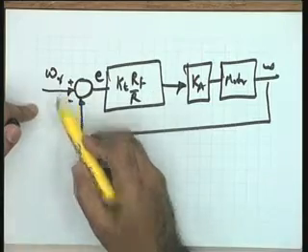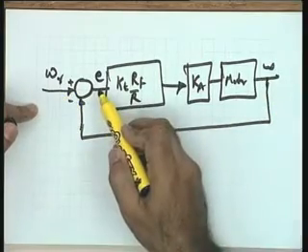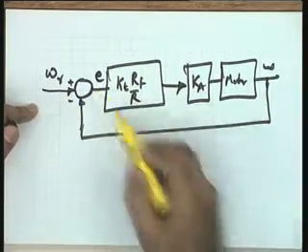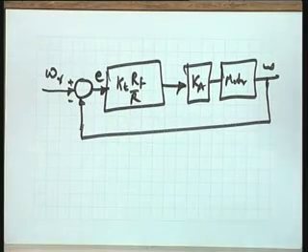Now, in this particular case, this is E and not E cap, because E is the system error. E is the error between the commanded speed and the actual speed, and the cap can now be removed, and in a unity feedback system you can get E variable over here.